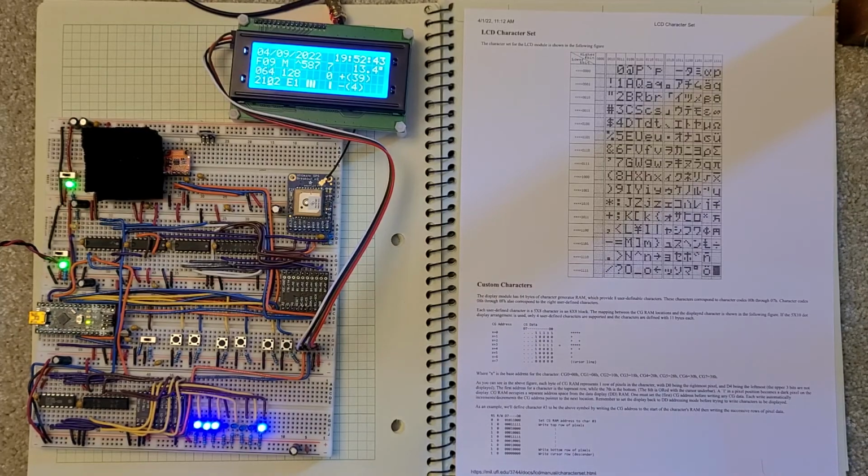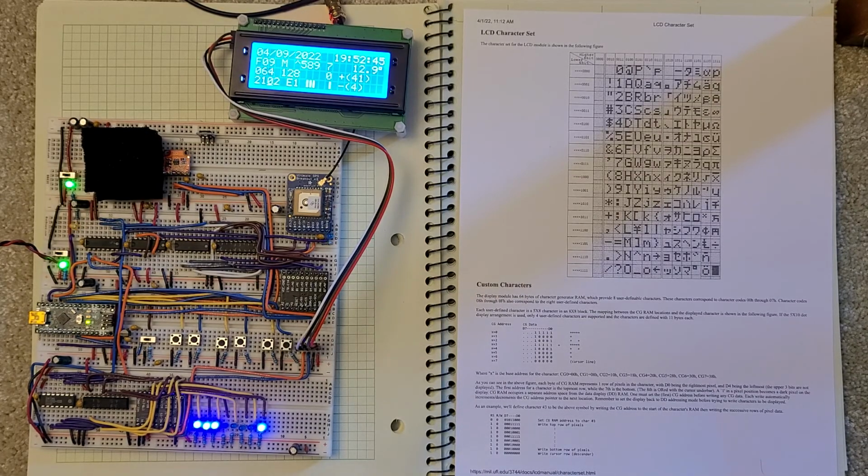All right, so it's time for an update on the GPS disciplined oscillator. Where we last left off, I had the LEDs that are showing the relationship between the 10 megahertz clock and the PPS signal from the GPS. And so shown here, if the PPS happens, the clock edge occurs midway through the next cycle. And then this clock is running a bit fast, so that edge, which is right here, is inching slowly towards the time when the PPS comes.